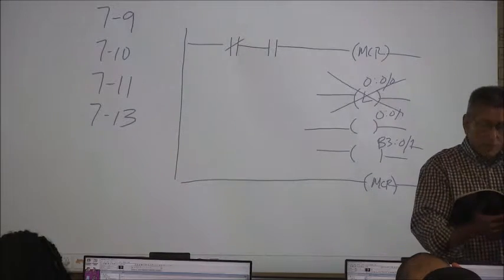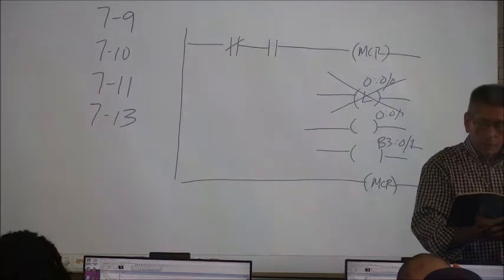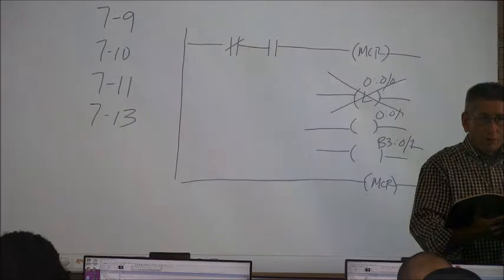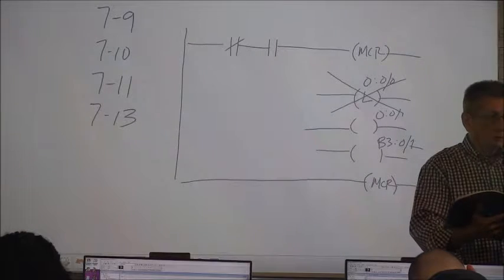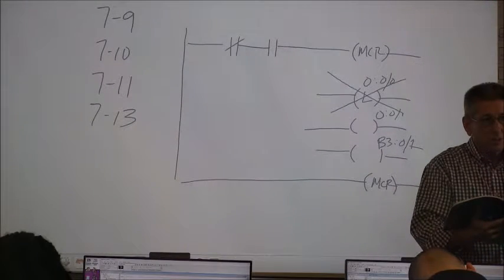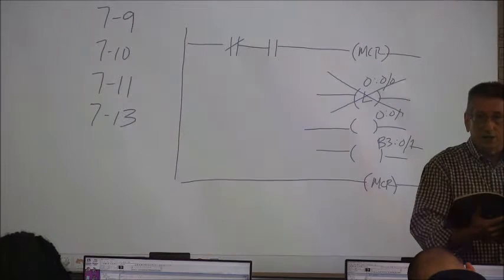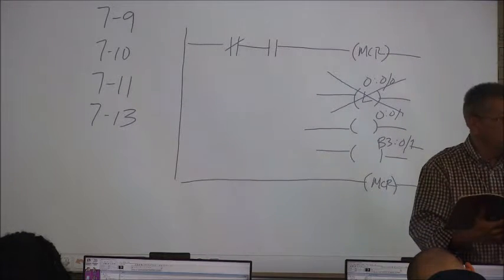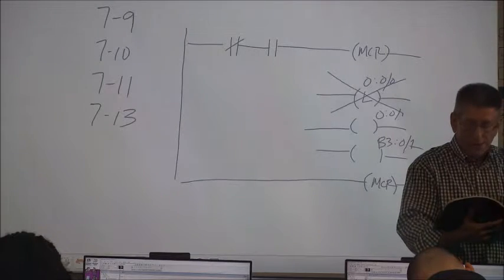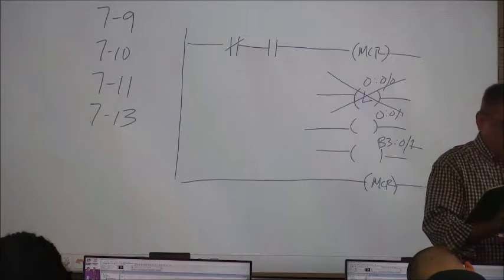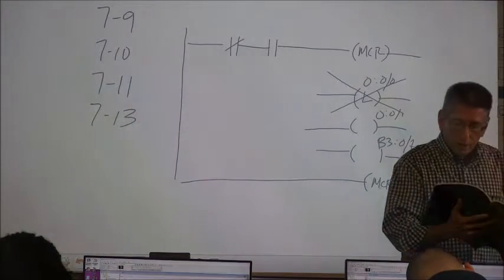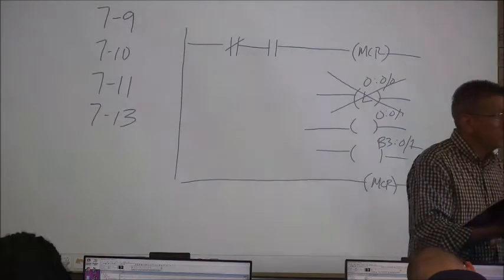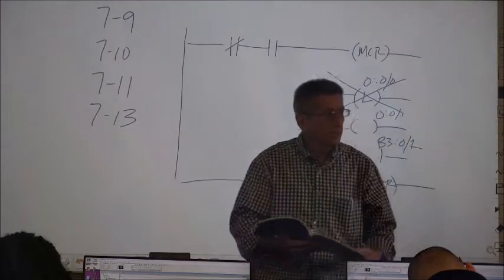So you see the pump input to that RTO, the retentive timer? The pump input can go true for a while, then goes back false, but it retains the accumulated time, right? What do you want us to actually set that at? Because we'll never see it running for 10,000 seconds. Like 30 seconds or something? Yeah, 30 seconds.